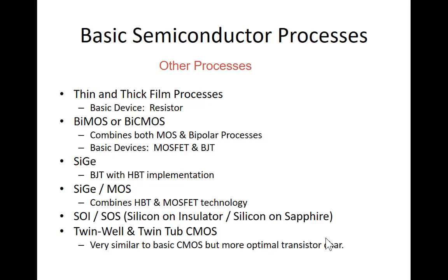And in the thick film processes, they're screened. You screen the resistor much like you screen the t-shirt or the sweatshirt that you have on. That went through a screening process. Instead of putting ink to make it look white, you'll put a resistive material in that has a certain resistance per unit area.